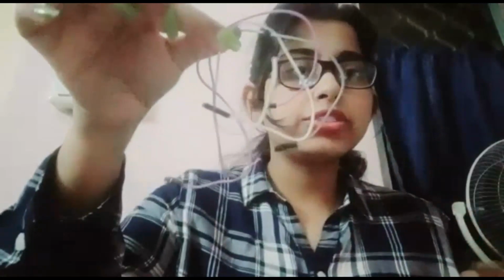Next is obviously our Bolt Wi-Fi module. That is basically the module or the main chip that we are using in this case. And the next thing that we require is three male to female jumpers. These are the three jumper wires that I will be needing to connect the sensor to my Wi-Fi module. And last but not the least, to provide power to my device, I will be requiring a micro USB cable, that is this one right here. Okay, so I need to connect this with my Bolt Wi-Fi module, and then I will be inserting this into my laptop from where it will be deriving the power it requires to run.